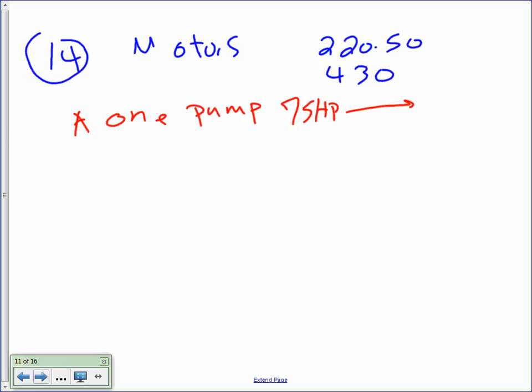And if you guys go to table 430.248 under 240 volts, you're going to find the amps are 40 amps. You need to find the amps for it. So take the 75. I'm sorry, not 75, 7.5. It can't be 75. Is it clear that 7.5 is the example that I gave you? Yeah, 7.5. So 7.5 at 240 under 430.248 will give you 40 amps. Can I have thumbs up, Chad? That's how we find the full load current. Piece of cake.